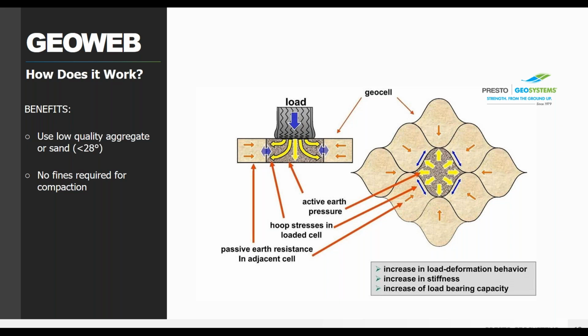Strong seams, semi-ductile resin properties, and those integrated connectors are all going to be critical to the uniformity, I'm going to keep mentioning it, uniformity in performance of the installed system over the entire lifetime of the project. The GeoWeb system and all of its accessories are specifically designed to work together to be an effective, permanent solution for roads in soft soil locations. And so in load support scenarios, which is what we're covering today, vertical deformation can only occur with either the compression or the compaction of the soil or through lateral movement of the soil. So basically getting pushed to the side and creating ruts.